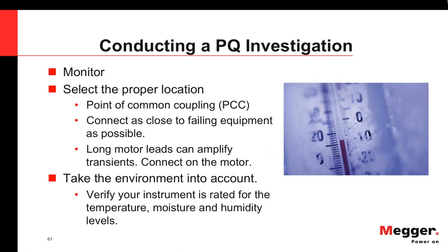Inspect the system. First of all, check for safety hazards. Check that everything's to code. A lot of times that can be an issue. And check for bad connections. Thermal imaging actually does come in handy for this, to look for a hot spot.